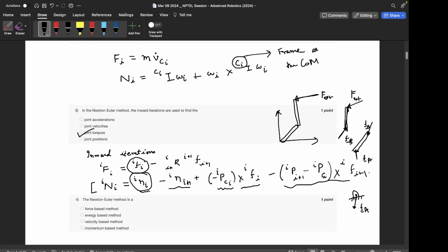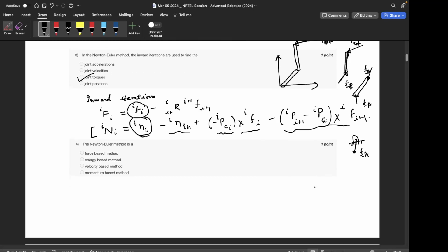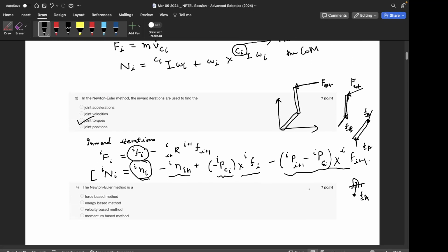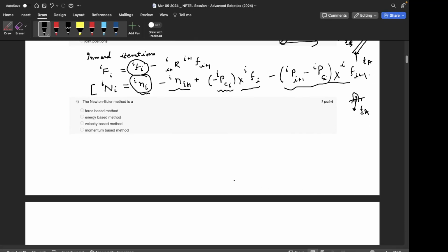There are rigid bodies connected by revolute joints, and whenever there are forces acting, you take out each link individually and you apply forces at each of those connections. Those are forces at the joints, and if there are any other external forces, you apply those too.